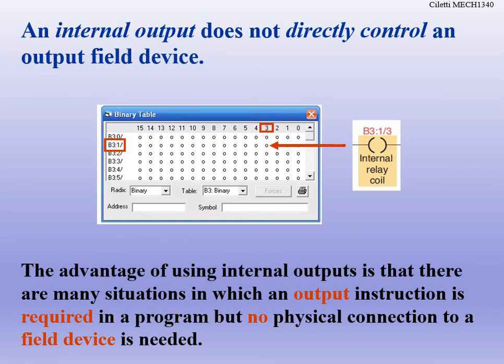This is an internal memory coil, okay? We just call it a memory coil in Siemens, but it doesn't actually turn on anything external. It doesn't turn on a motor. It doesn't turn on a solenoid valve or anything like that. It's strictly stored data that can be used. So what you can do is say, all right, I need this condition, and I need to store that it happened into a memory. So I can take that and store it into a memory coil and then use that memory coil to start other things when that condition is true. So it is only internal to the processor. It doesn't impact any outputs. You're just storing that this condition happened. That's really all it's doing. It's like registers and position registers and things like that we did in the FANUC programming. We are just storing data. That is it. It is not tied to any specific outputs when we do that.